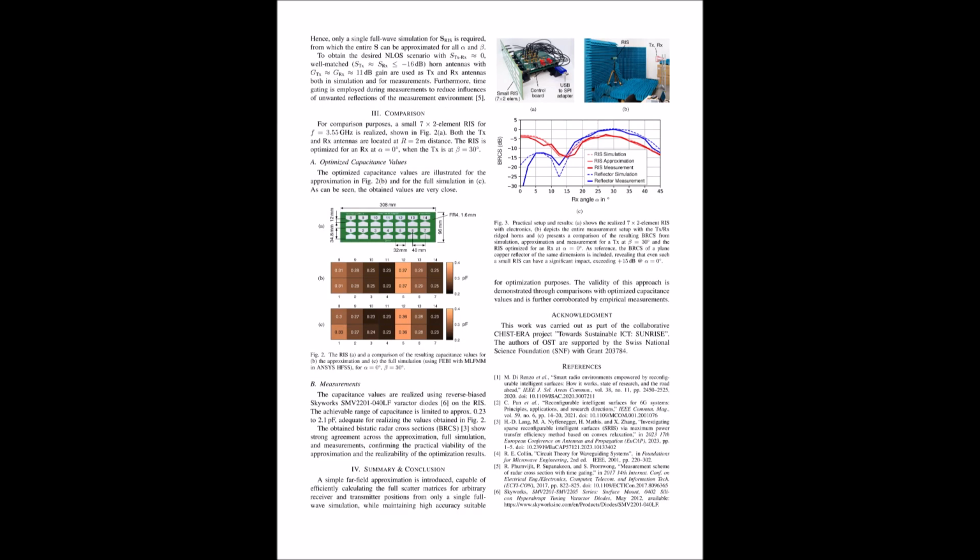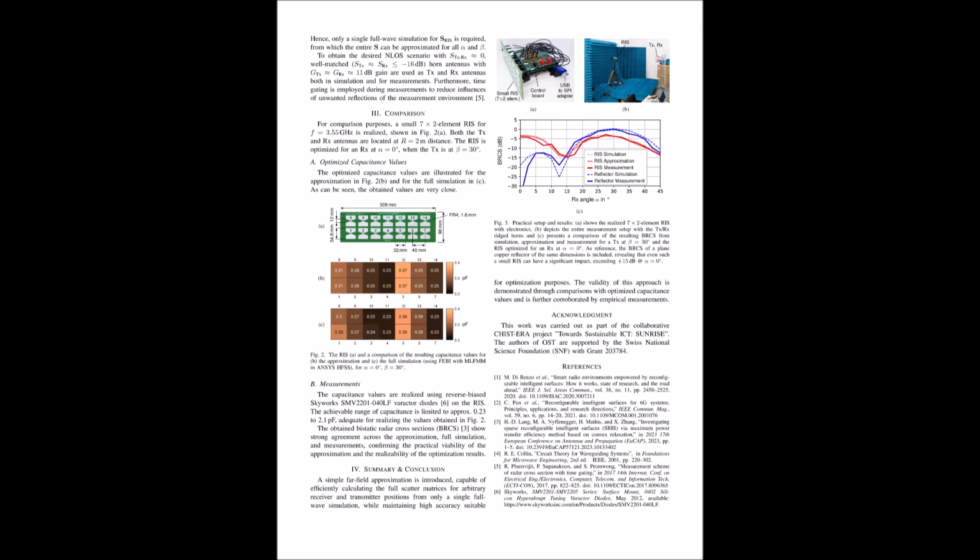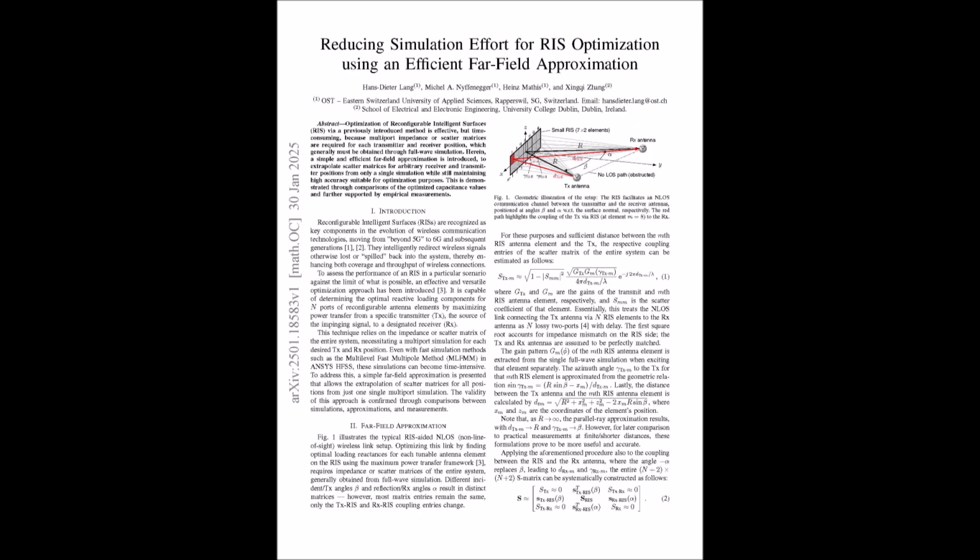Oh, that's just about distance and wavelength. d_TX,m is the distance between the transmitter and the RIS element. And lambda, that's the wavelength. It's basically saying that the signal gets weaker the farther it travels. Makes sense. The farther you shout, the quieter it gets, right? Exactly. Now, this last part, e to the j times 2 pi d_TX,m over lambda, that might look scary, but it's just dealing with the phase shift of the signal.